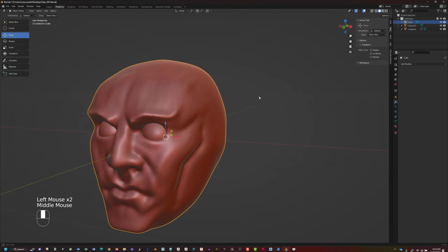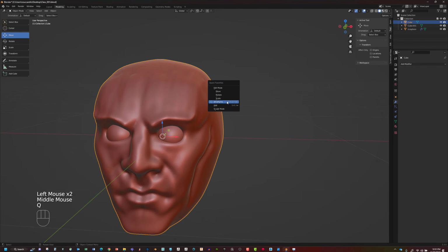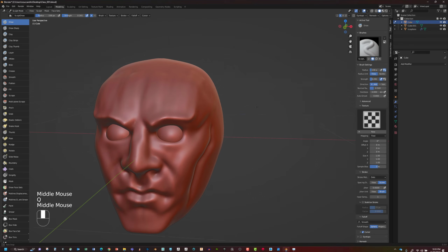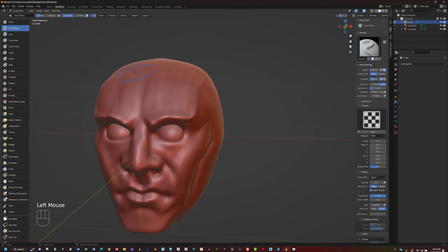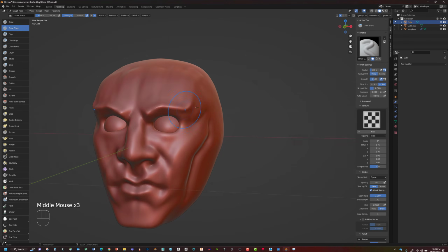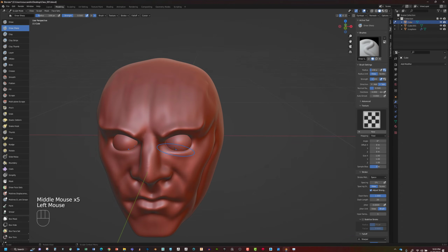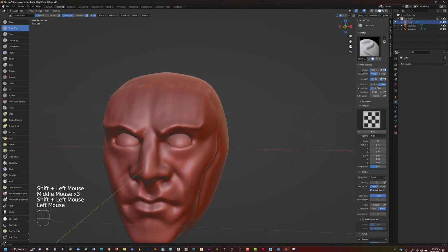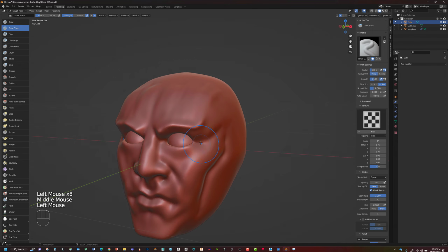Now if we want to go sculpt the head, we select it, and then we can go into the sculpting mode up here. You might again have it on your quick favorites to go into that. And then now if we start to use the draw sharp, that's going to allow us to just sculpt right on the mesh and form a shape around this eye. And we don't have to worry about messing the eyeball up. And so that'll be good for us.